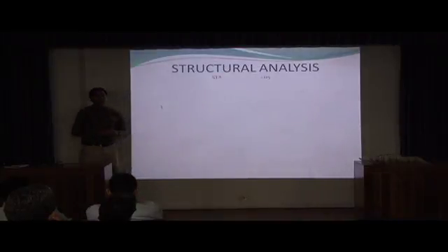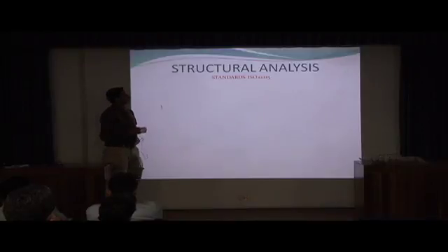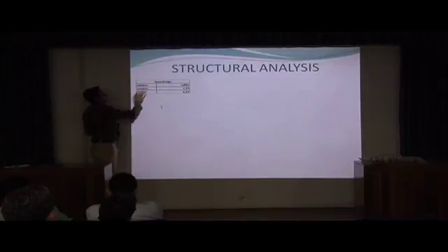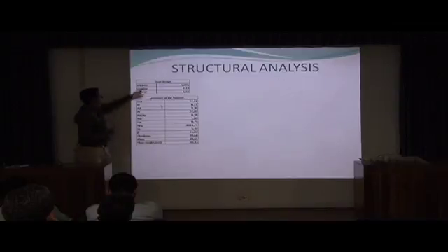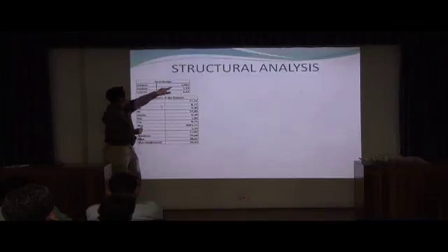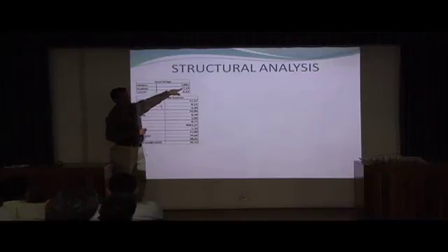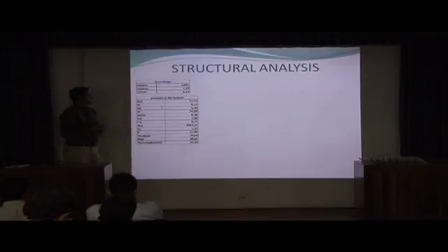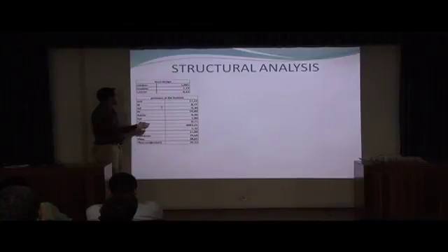Then the structural analysis. For the structural analysis, I use the standard ISO 12215. I read an article, and here in the boat design, I have to be in the range, with the minimum and the maximum, and we see that I am in the range. That means that I can use the standard ISO. Then I did the calculation of the different pressures of the ship.